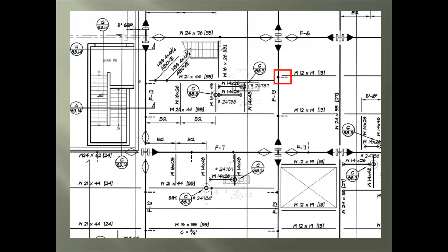This symbol is for the diagonal bracing tying the beam to the girder, and if you notice the dash line, it represents that it's under something solid, like the deck slab here in this situation. Here, taking the same rule and reversing it, now when it's solid, as in a line, or in this case a box, it represents that it's coming up at you on top of that solid item, and here again it's the deck slab.